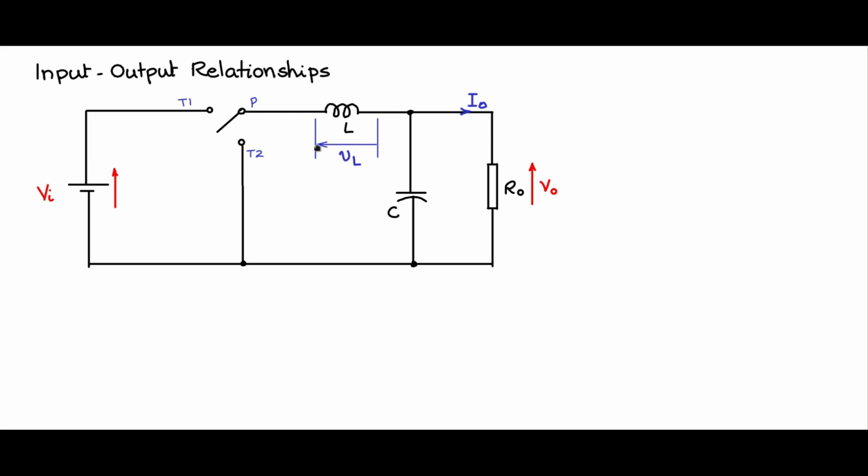So I could as well have used the arrow mark in this fashion, which means that if the arrow is pointing to the right, then you keep the common of the probe on the left and use the measurement probe on the right. But here what I am doing is keeping the common probe here and the measurement probe here.